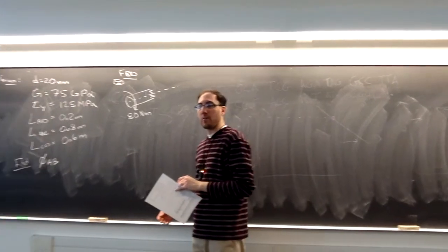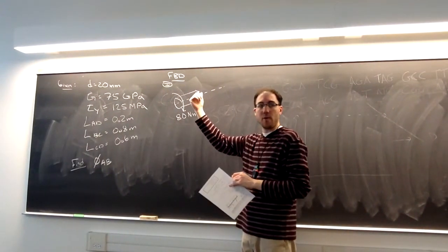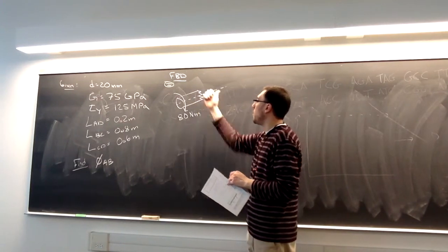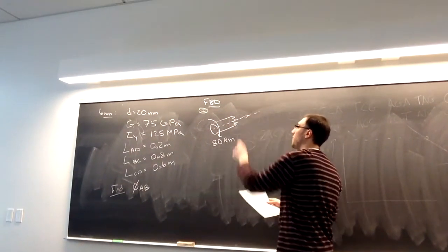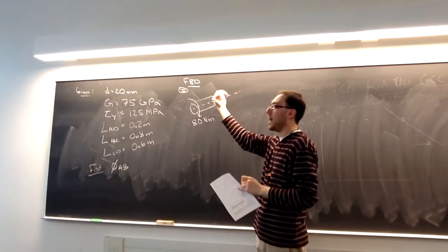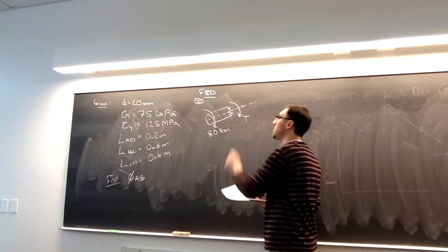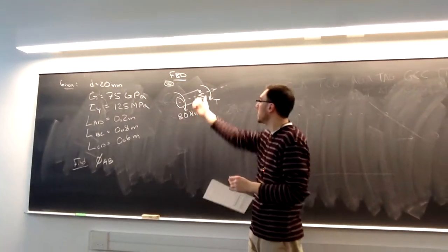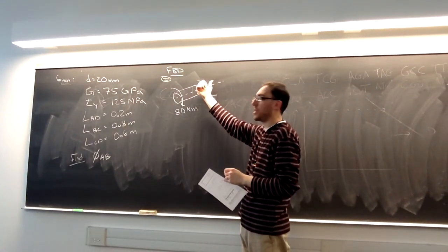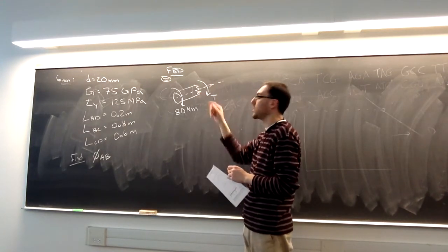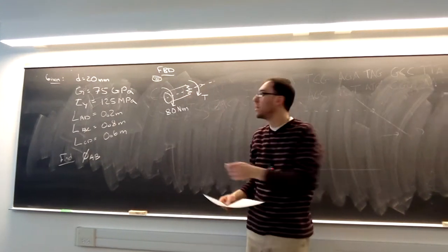And remember, how did we decide the direction of torsion? Similar to how we do the direction for our internal normal force. We put our thumb in the direction of where that internal normal force would be, and then with our right hand rule, that's the assumption we're going to make on the direction of that internal torsion. So from the cut, my thumb is in that direction, so my fingers curl in this direction. That's the direction I assume the internal torsion, BC.